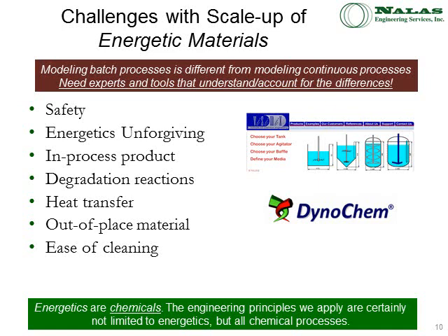There are also degradation reactions that are associated with both pharma-related and energetic materials. When you're scaling up, you get into a bigger reactor and you have longer dose rates, longer dose times. You might have to have a longer hold period, for example. These degradation reactions become a bigger problem with impurity profiles and even loss of a reactor again.